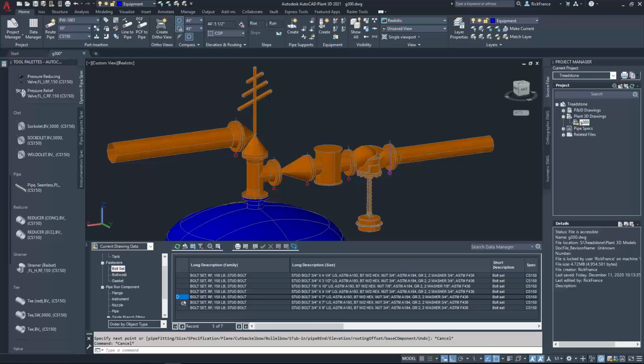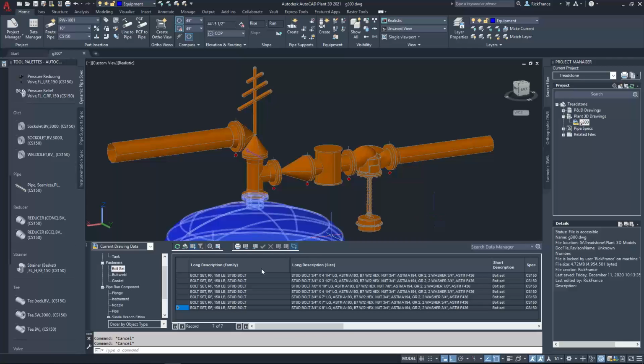It's the H to I and the I to flange. They were 5-inch before. I made it longer, 6.25, so now they're calculating up to the next one, which is 7 inches, because I made the length of the bolt longer in that one. And then the last one is, this is where I added 4 inches from 1.12 to 4 on the flange thickness of the component. So now it's going to the next available size, which is 9 inches. So I'm able to affect all these different sizes using different methods.